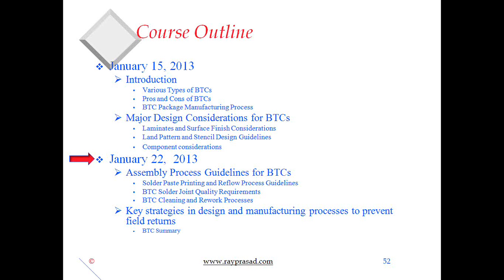In terms of design issues, if it's lead-free, think of this as using a different kind of package that can handle lead-free temperature, and the moisture-sensitive handling of that is important. The laminate, you need to spend some more money in getting the PCB, that's the more expensive one, so that it can take the lead-free temperatures.